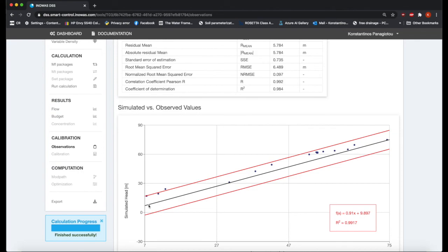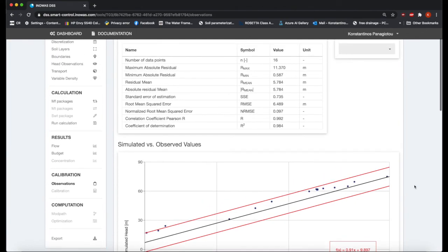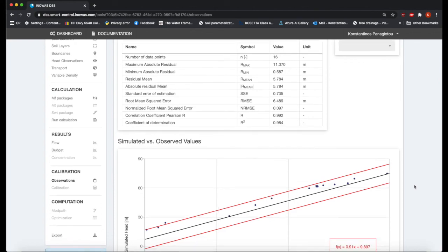And in order to make this happen, we probably need more cells, because if you put more cells, then you allow the hydraulic head to decrease even more, so that way, by reducing the error in this region, you're automatically decreasing the root mean square error. But it's not bad.